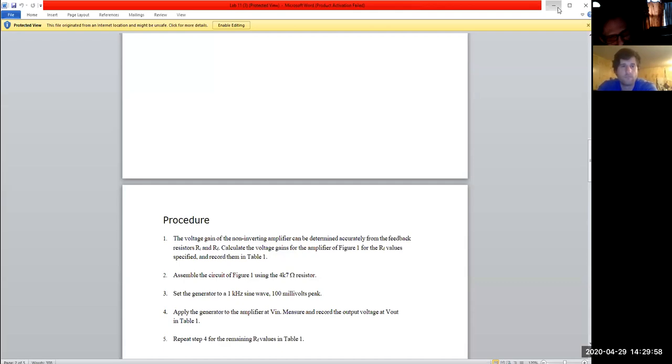We used to get these machines, especially when you send stuff to Asia, oh my God. Their power there is so irregular. Our machines were hooked up to their power out there and they kept getting glitches, but only in Asia. Then we came to find out that because of the way their ground was, they do all delta out there. They never do any Y configuration.